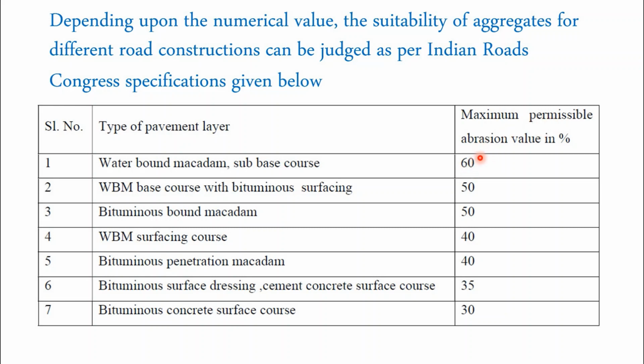Okay, so this can be provided for water bound macadam sub-base course alone. And for water bound macadam base course with bituminous surfacing, the maximum abrasion value should be limited to 50. And for bituminous bound macadam, the maximum abrasion value should be limited to 50%.